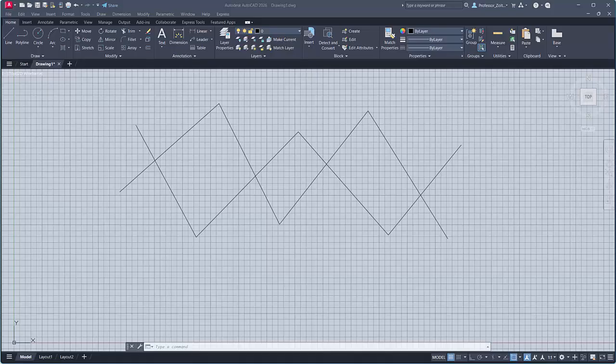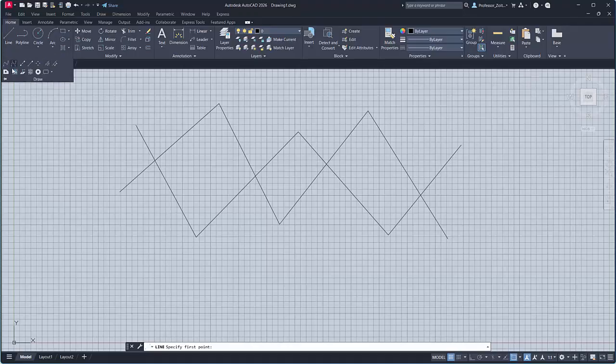So let's do a very brief recap of what we just did. The first thing I wanted to do was draw a line. So I had to go into and click on the line command. But remember, I'm trying to use the phrasing that CAD does, and therefore I said draw a line. And the reason I did so was so that we entered the draw submenu. And this draw menu has the line command within it. Now if I click on that, it's like a drawer. If I open that up, there's also other line commands in there too that are not as commonly used, but you could use them. But I want to click on the line command. And again, I'm looking down here to make sure, oh, it says line.